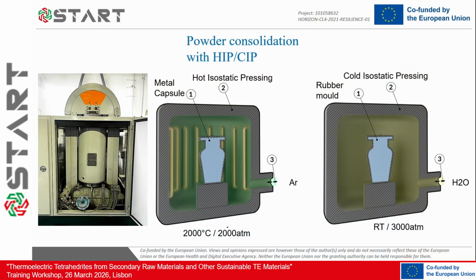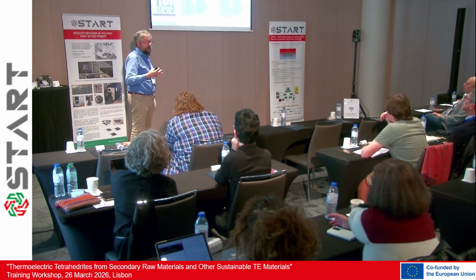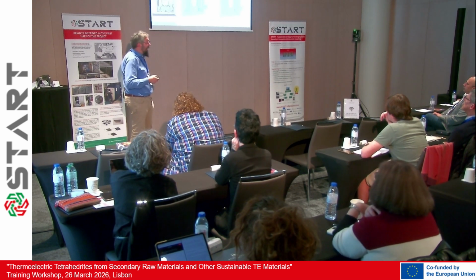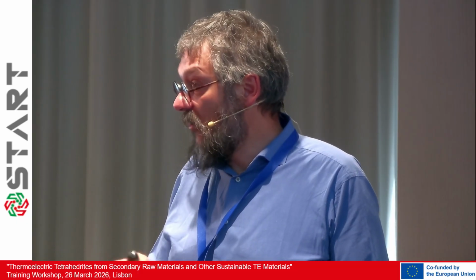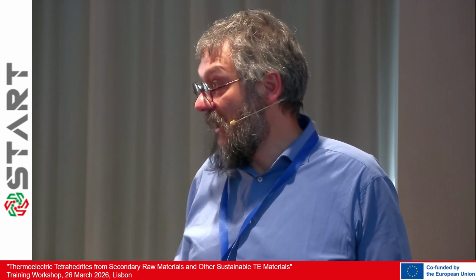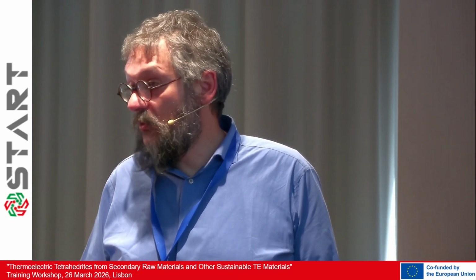This is a picture of the equipment we are using. But of course, if you first do the cold isostatic press, you already have a sort of consolidated pellet that you can put into the hot isostatic press to have a sort of thermal treatment in pressure without the need of the capsule. The capsule is needed because if argon gets into the open porosity, basically it is not affecting at all the compaction effect of the material. It's just keeping those porosities open. You need to have it closed.